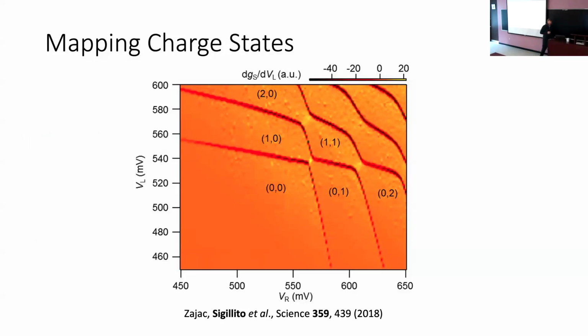because they allow us to map out basically the electrostatic landscape of the device. And what we're going to do is an experiment here, where I take 2 of those sites and 2 of the plunger gates, the left plunger gate and the right plunger gate of 2 sites, and I'm going to vary their voltage. As I change that voltage, if I think about that quantum well, as it becomes more and more positive, electrons want to live under that gate more and more, to the point where, as I get to a certain potential, instead of 1 electron in the device, I could have 2 electrons in that potential well, or 3 electrons.